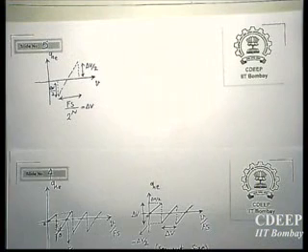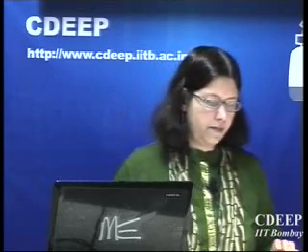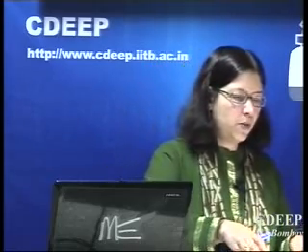Because you can even control the sampling rate, and sometimes you can even go below the Nyquist rate, having statistical information available. Practically, this is in fact better. Only it needs a lot of hardware overhead, because you need memory, you need to store this data, and then you need to use the samples. There will usually be a DSP processor on top of this system, which will control the data converter itself.